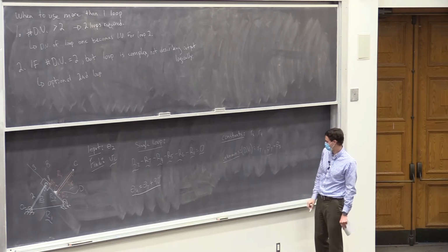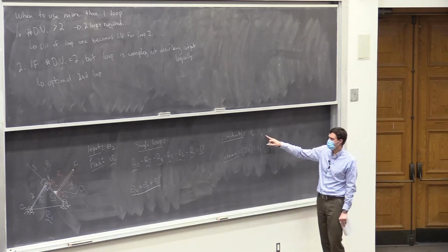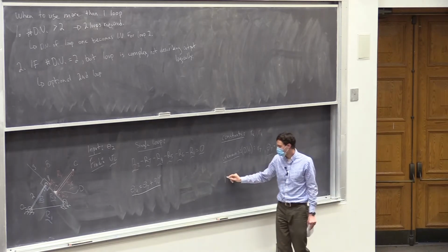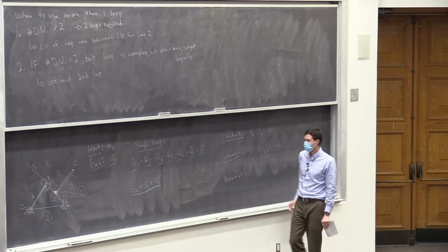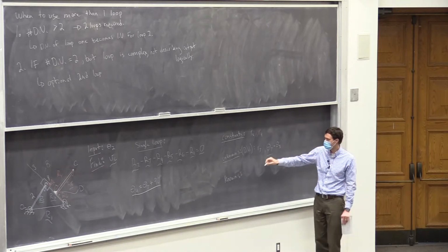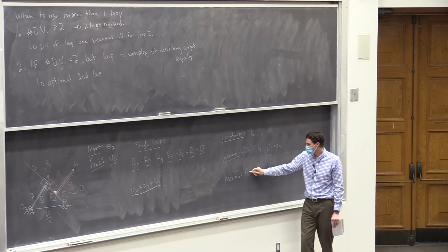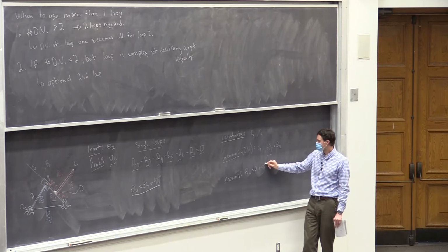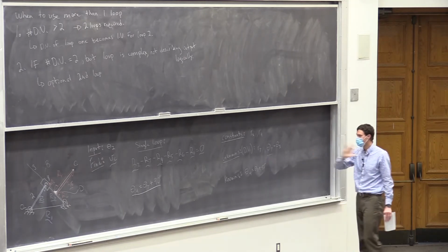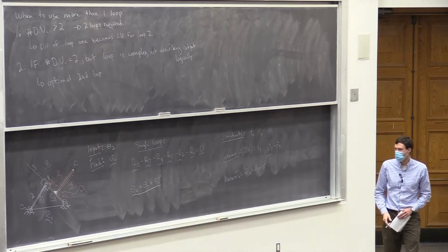So it's not necessarily constant. So maybe we'll make up a new category. The book doesn't call it this, but this is how I like to think about it. Additional knowns, because we have some relationship. Theta 4 equals theta 7 plus 90 degrees. Okay, so it's not an unknown. Once we already have theta 7 as an unknown, theta 4 can be calculated from it.